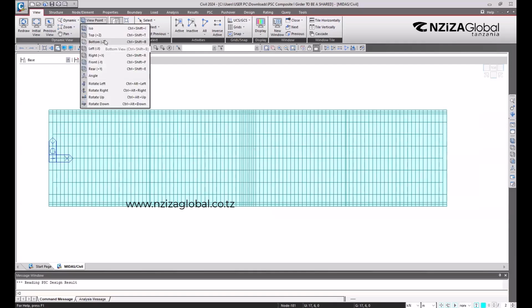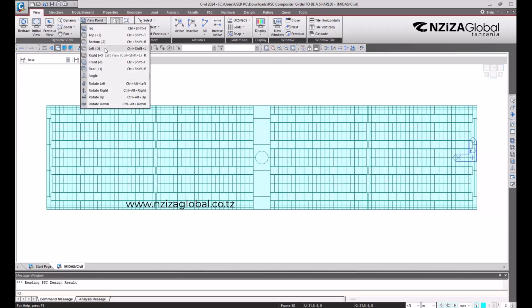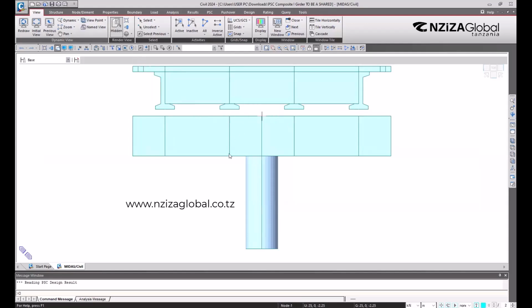If you want to look at the bottom view or -Z, I can use the shortcuts as Control Shift B. You see, I see the bottom, you see this is the pile. Then if I want to view the left view, you see I can place here, or I press Control Shift, then left direction arrow. Then if I want to see the right hand side, I can click here, or I can use these shortcuts, Control Shift L, which stands for right.